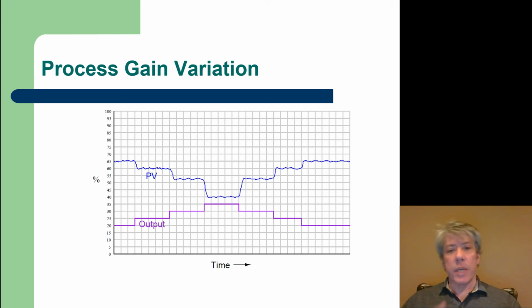So then as we continue, the controller just keeps stepping up by 5%, but the flow rate changes more drastically. It's a nonlinear thing. The sensitivity of the process depends on exactly what range it's operating in.